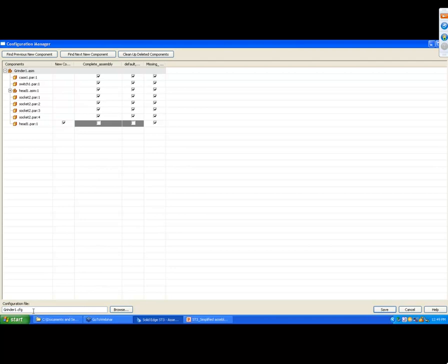One thing I would like to mention here is whenever you see this configuration.cfg file, that's one of the main reasons why I ask people to use Revision Manager whenever they are copying an assembly file from one location to another. So even though you will think that this is not linked, Revision Manager takes care. It doesn't list it in the tabular form, but it will move this configuration file from one location to another when you use Revision Manager to copy your documents. So again, that's very important.